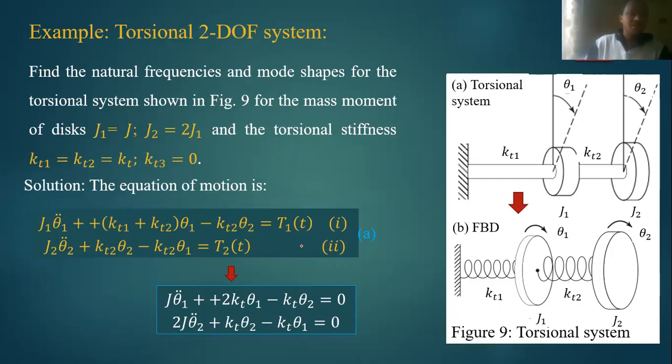To illustrate our discussion, let's take a simple example of a torsional system. Look, a shaft which is fixed here and which has two flywheels here, and we have the shaft stiffness KT1 on this side and the middle stiffness KT2, and the shaft has θ1, the relative twist, and θ2 of the second shaft.